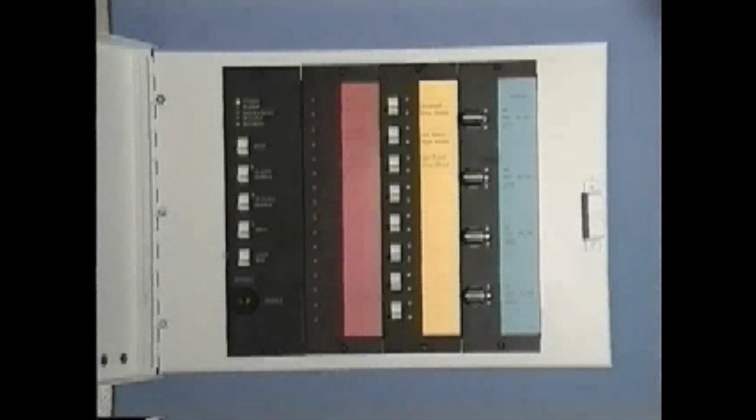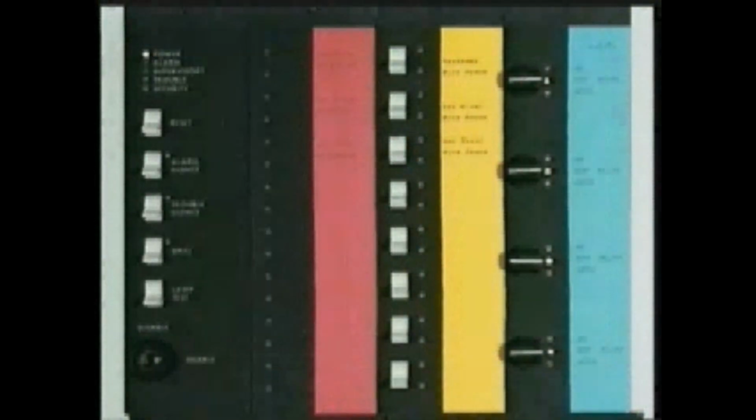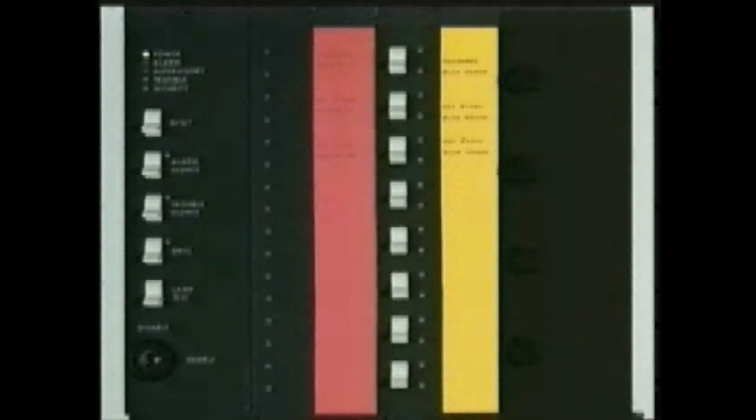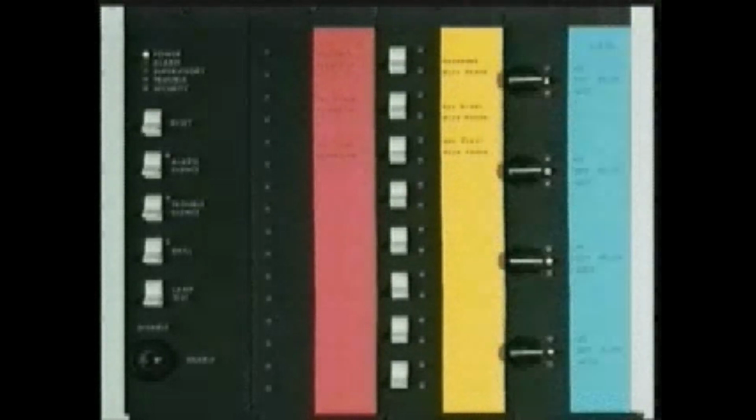Let's take a look at what makes up a SAN remote annunciator and how it works in conjunction with the EST2 system. A SAN remote annunciator may consist of several components. This particular SAN4 has a 2-SANCOM control module, an SLU16 remote annunciator LED module, an SWU8 remote annunciator LED and switch module, and a SHOW 4 remote annunciator LED and switch module installed.